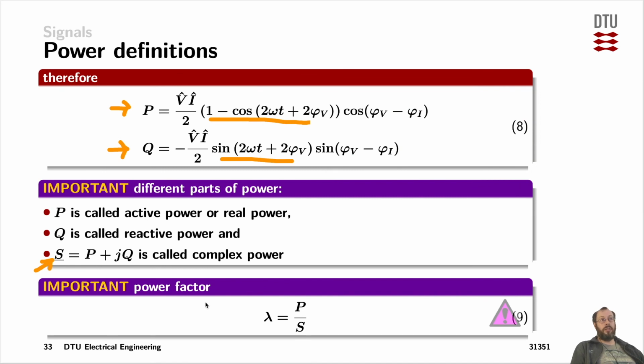That also leads to the definition of a power factor. Just as we had the crest factor here, we are relating the real part of the power, the desired part that we actually want, to the total amount of power, the complex power, and that is called the power factor. In modern power factor applications, and also looking at the laws about those power factors, we are speaking about power factors that are bigger than 95%, sometimes 90%, or even 99%, depending on which application we are speaking about.